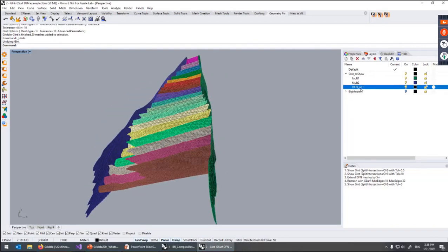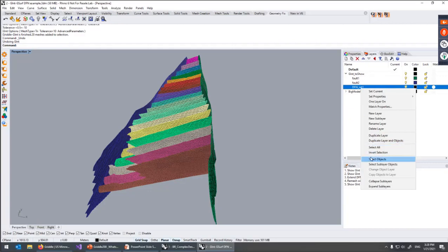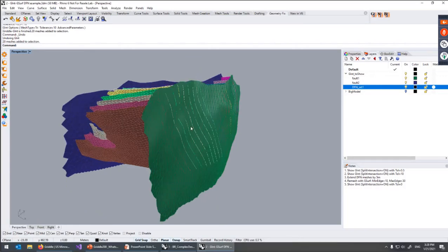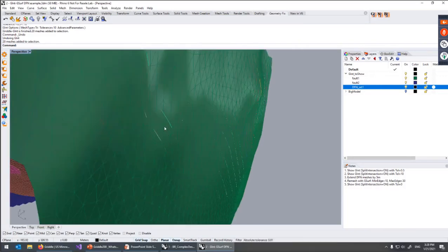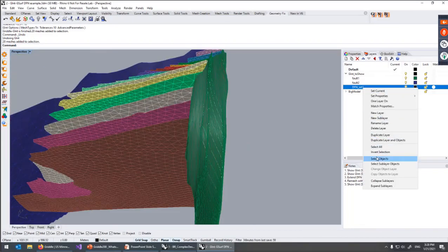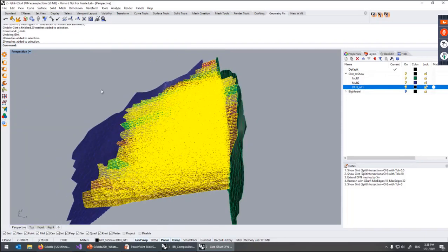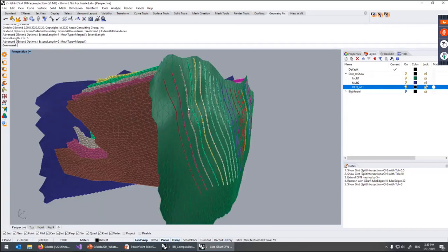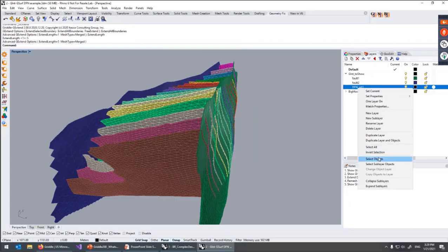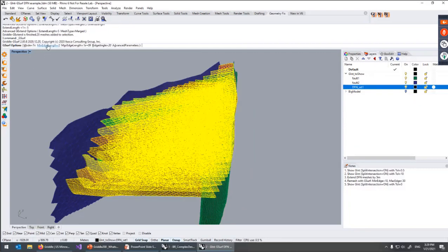And what I'm going to do now, I'm going to slightly extend DFN meshes. You can see they already slightly protrude or intersect the faults, but not completely. So I'm going to extend the DFN meshes so they for sure intersect the fault meshes. I will describe later in more details how this works, but for now, just follow me on this. So you see now all the DFN meshes protrude through the faults. I can remesh the internal meshes, the DFN meshes.